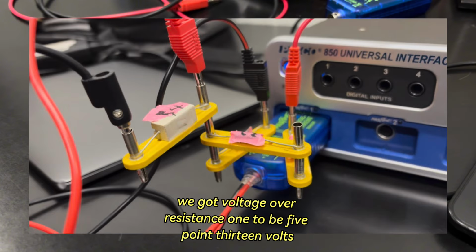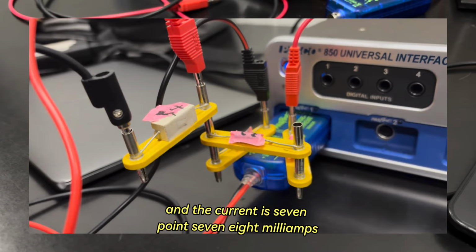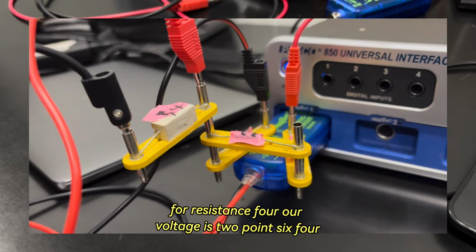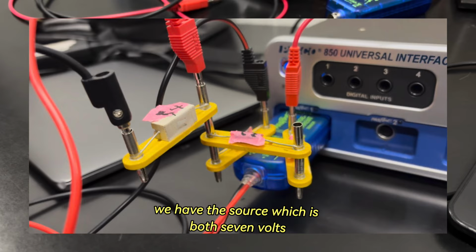We got voltage over resistance 1 to be 5.13 volts and current across resistance 1 to be 34.2 milliamps. Now the voltage across resistance 2 is 5.29 volts and the current is 7.78 milliamps. For resistance 3, the voltage is 4.36 volts, the current is 7.78 milliamps. For resistance 4, our voltage is 2.64 and our current is 26.4 milliamps. And for both of those, we have the source, which is 7 volts.